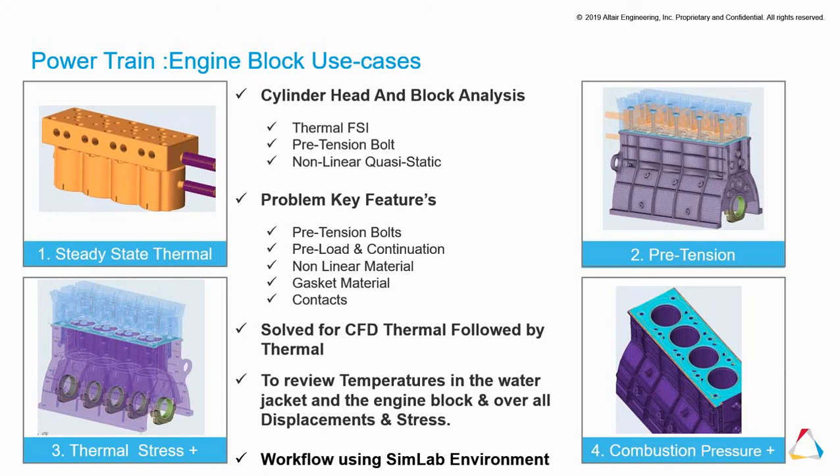You have a steady-state thermal analysis. It's AcuSolve based. You can take advantage of running AcuSolve if you have complex thermal problems and some flow analysis there. And then we do pretension. Then there is thermal stress analysis coming, followed by the pretension, and then those thermal stresses are coming from the CFD tool, automatically mapped beautifully in SimLab, and the combustion pressure analysis, followed by the continuation of all these analyses